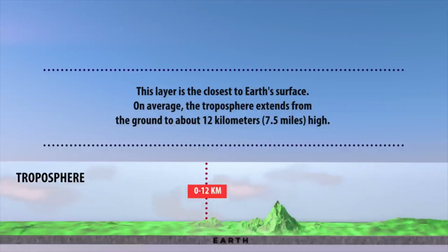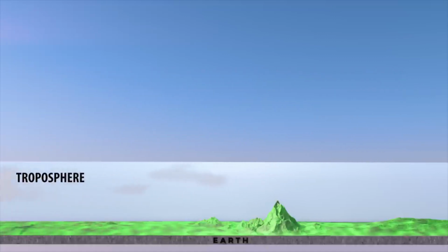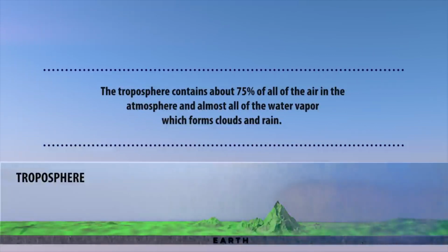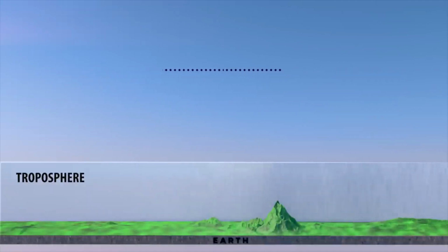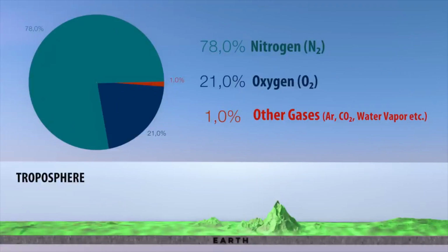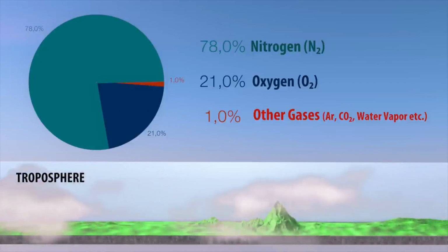In the standard atmosphere, sea level pressure is 29.92 inches of mercury, Hg, and the temperature is 15 degrees Celsius, 59 degrees Fahrenheit. The standard lapse rate for pressure is approximately a 1 Hg decrease per 1,000 feet increase in altitude. The standard lapse rate for temperature is a 2 degrees Celsius, 3.6 degrees Fahrenheit, decrease per 1,000 feet increase, up to the top of the stratosphere. Since all aircraft performance is compared and evaluated in the environment of the standard atmosphere, all aircraft performance instrumentation is calibrated for the standard atmosphere.